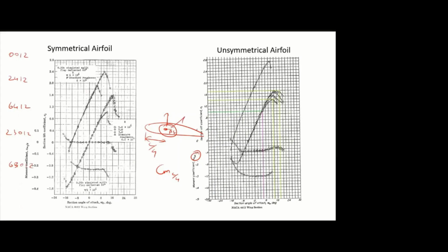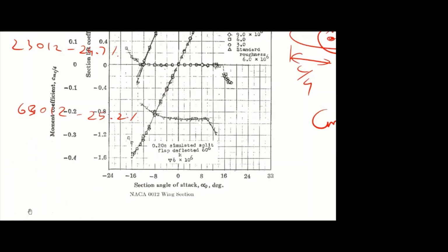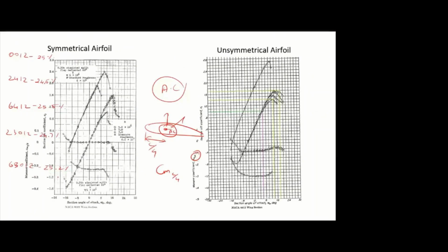And we have the derivation for how to find the aerodynamic center. So you find the aerodynamic center for the first aerofoil. This may be 25%. For the second aerofoil, it may be at 24.5%. Here it may be 25.5%. Here maybe 24.7%, here maybe 25.2%, like that. If you find the aerodynamic center, it will lie close to 25% of the chord. Is that clear? So if you find the aerodynamic center theoretically for any model, it will lie close to 25% of the model. Another simplification.